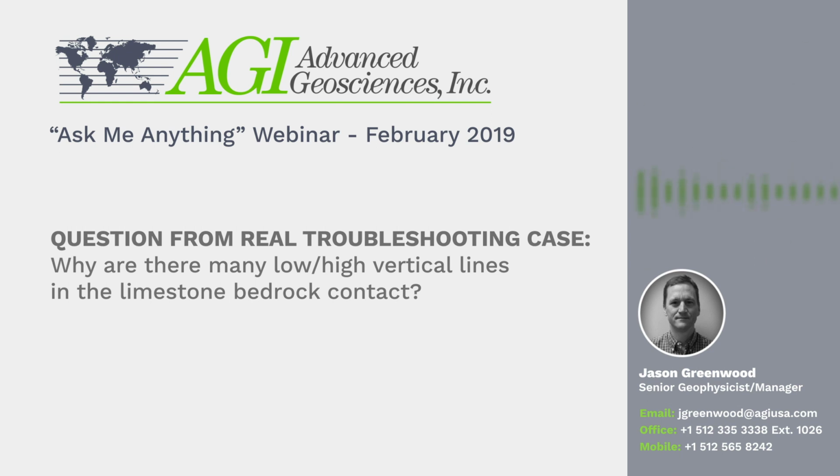perfect, almost homogeneous layer earth case. Like in some marine settings where you have a water layer, that water layer is homogeneous and that's the bulk of the model, and you just want to solve that sediment water interface, something like that. You might get better ground truth correlation with a pseudo section starting model, but it is not the default in Earth Imager. If you change to a pseudo section starting model, it'll greatly change the end result. Changing your starting model highly influences the final result.